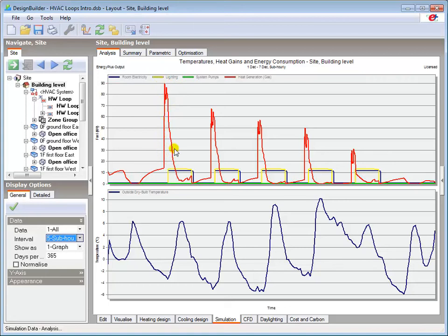This shows the heating system operating in the early hours to maintain the setback temperature in the building, then peaking to reach the set point temperature just prior to occupation. None of the peaks in the graph flatline at the top, which indicates that the system is not significantly undersized and is able to meet the heating load at design conditions.